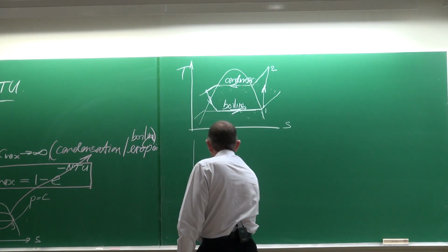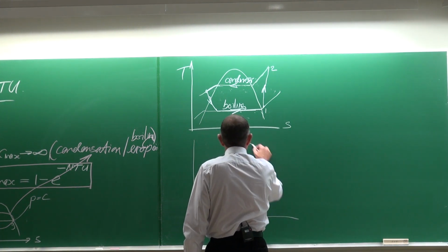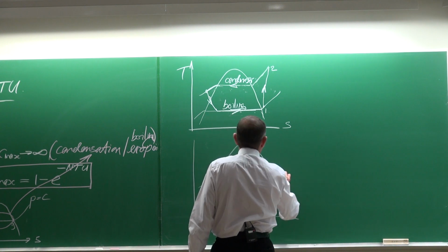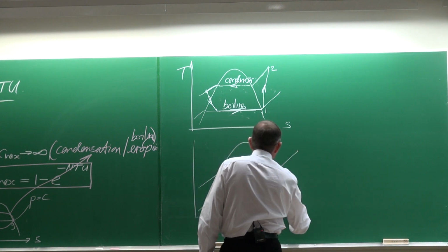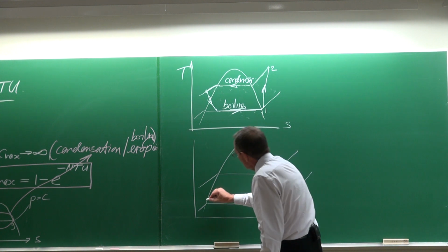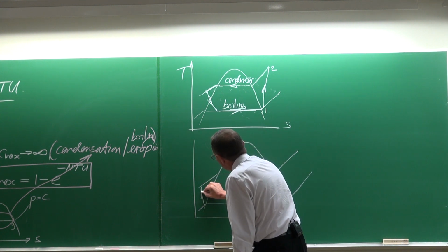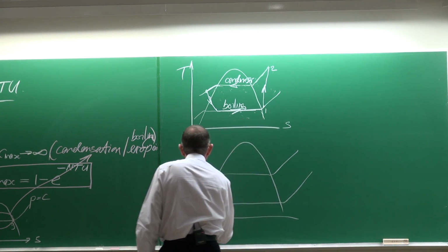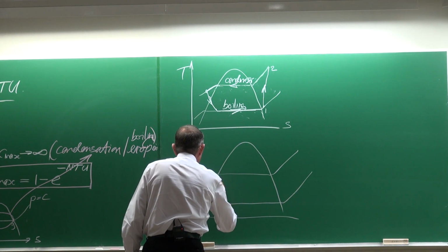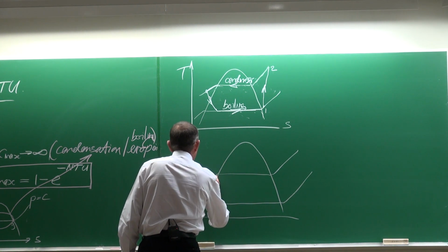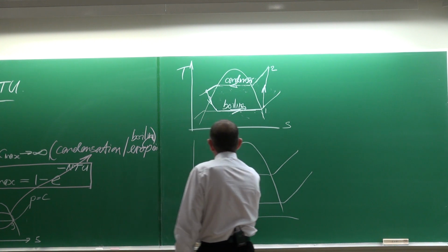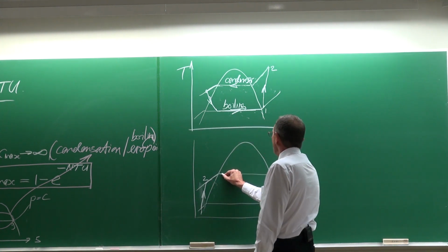Rankine cycle is in principle exactly the same. Our TS, there's our two pressure lines. Here we will have a pump. Not like that, because the entropy will always increase from 1 to 2. That is our pump. Then it is being pumped to the boiler.